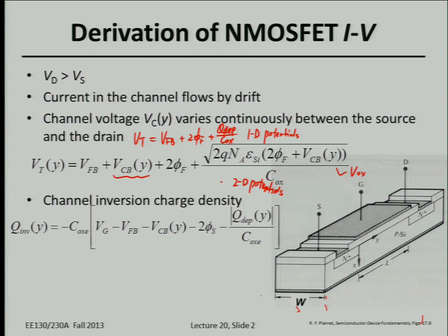Okay, and so what's the consequence on the inversion charge? Because we know that based on the expression, the inversion charge is equal to the areal capacitance of the gate oxide times the gate overdrive voltage, right? So that's the gate bias subtract all the terms appearing in the threshold voltage expression. So once you have non-uniform threshold voltage, of course the induced inversion charge along the channel will also be quite non-uniform.